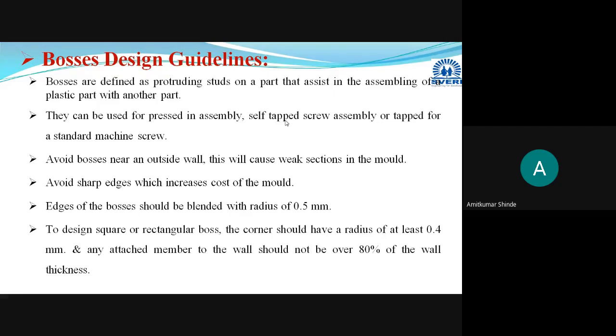Now, while designing this boss, you have to take into consideration some points related to its dimension, its shape, and its location. You have to avoid certain things, and you have to follow some standards. Avoid bosses near an outside wall. The location of the boss should not be very near to the outside wall. Due to that, that particular section will become weak.